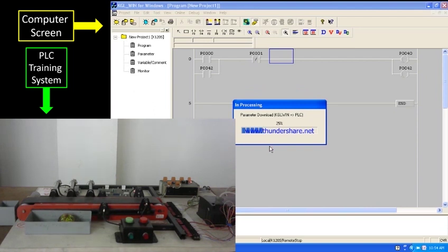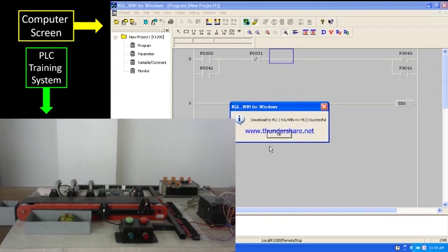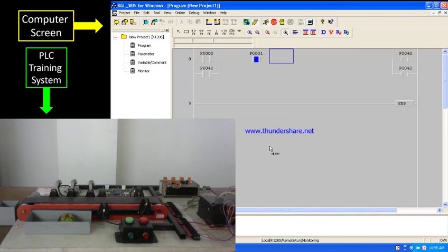So currently in this setup the P1 will be normally turned on. So after a single press of P0, the system will continue to run. Now if the P1 is pressed, then as we have seen earlier, the connection will be lost at the middle and the whole system will shut down.